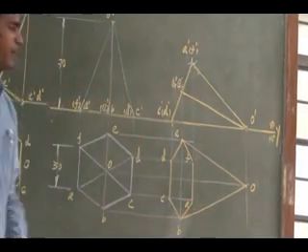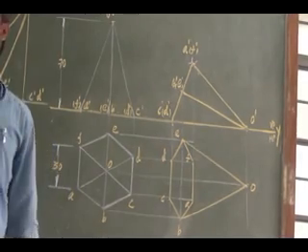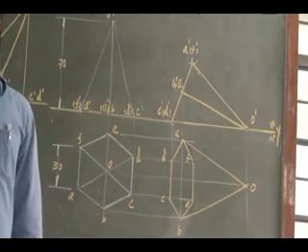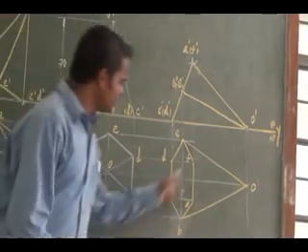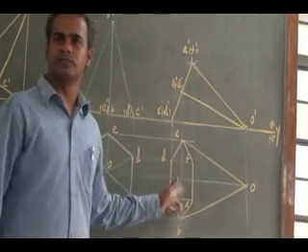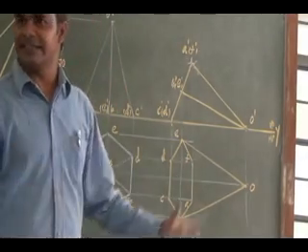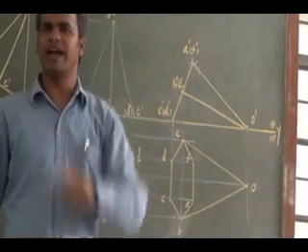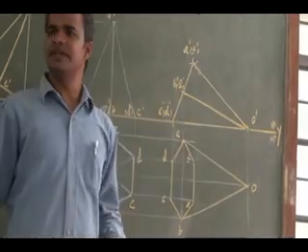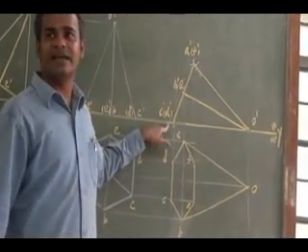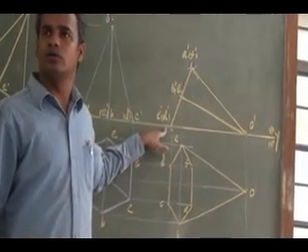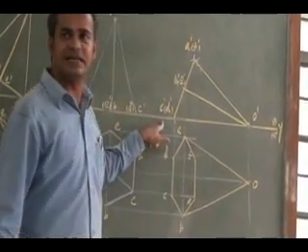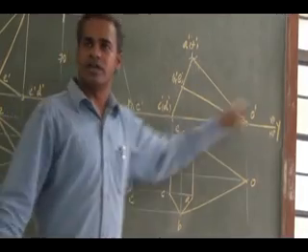Then, as per the third hint, to join the slant edge or side edges, it is a fully visible base. Whatever slant edge is crossing the fully visible base is going to be my hidden slant edge. Another statement says whatever slant edge I have below the axis, the slant edges are CO and DO.